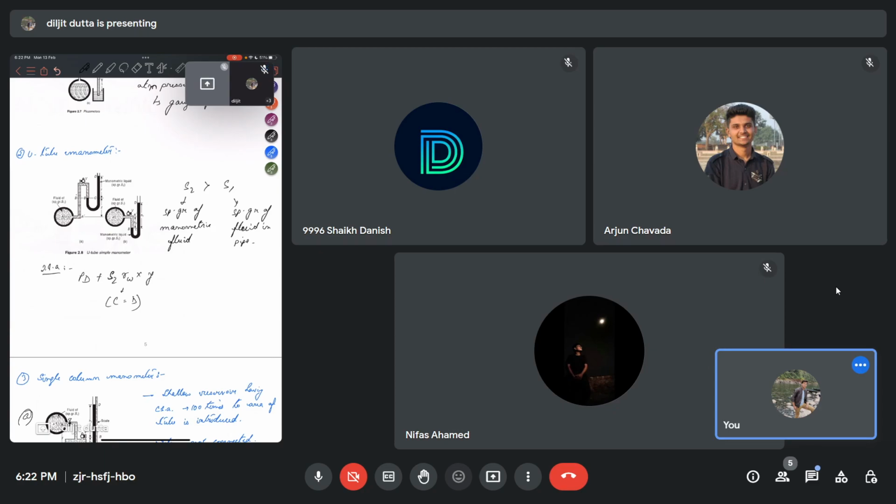Now point B and point B dash will have the same pressure, the only difference being the difference in fluid. So we have C equals B at the same pressure, and B dash also the same pressure. From B dash to A dash we are moving down, so again S1 into gamma water into Z, which equals P A. So this is how a manometer is used.